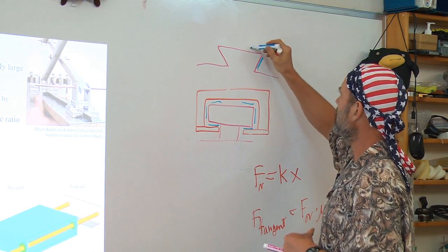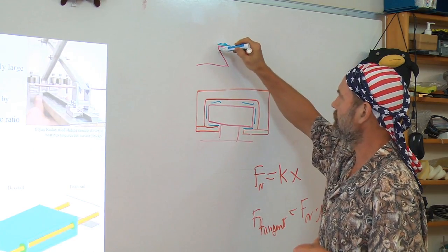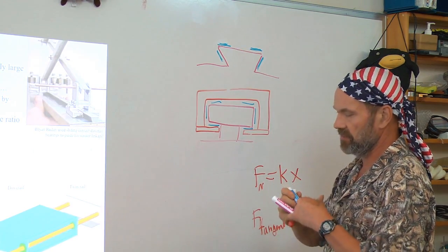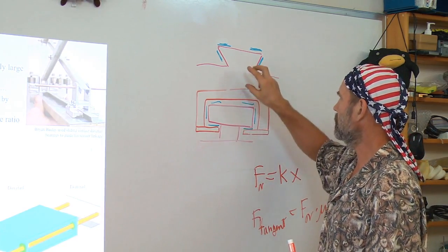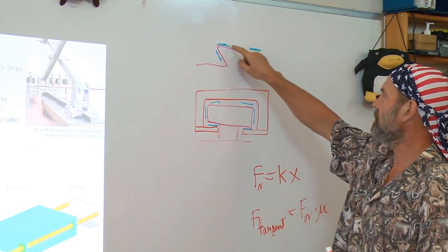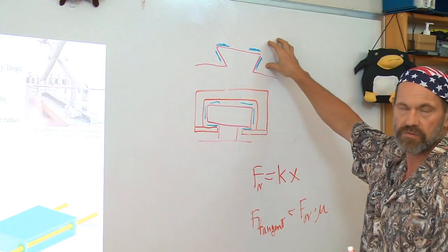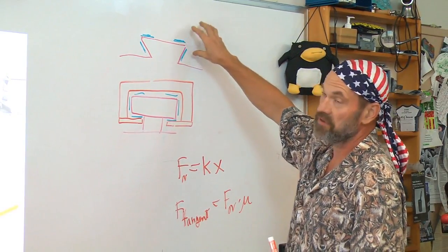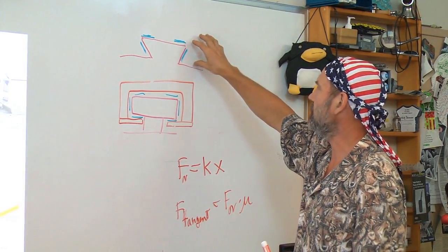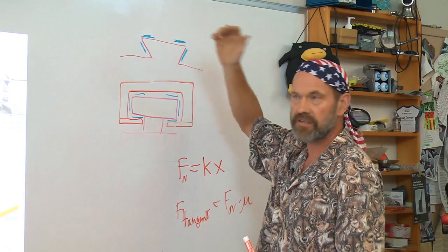And when I say a bearing pad, it's implicit in here that this is a separate, like a plastic element, but it doesn't have to be. It could be, for example, cast iron, and then there's either a steel carriage running on it, or it can be cast iron if it's well lubricated, or you could have plastic pads on it.